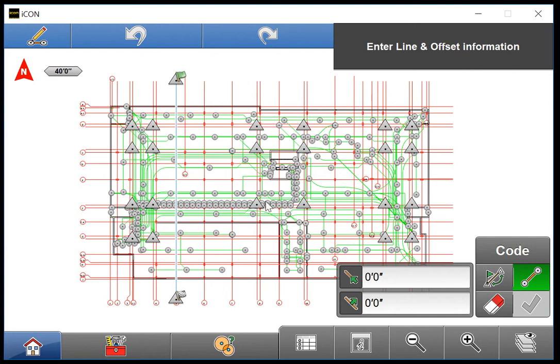Notice that if I select a line in the background, my starting and ending points are always the ends of the line selected. When using grid lines, this doesn't work for creating an offset from a control line intersection, and that's why I use the points to define the line instead of the line itself. If I'm creating a point that should be located inside a wall or a specific distance from a column though, this works perfect. Notice when I select a column or wall that it gives me the corners.